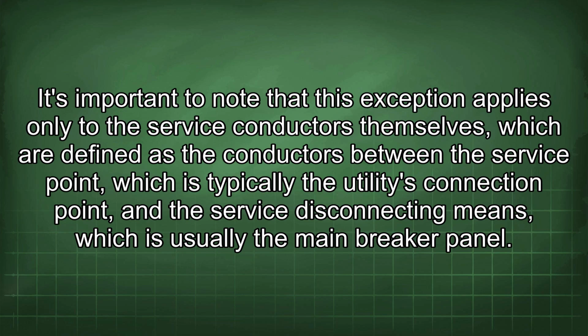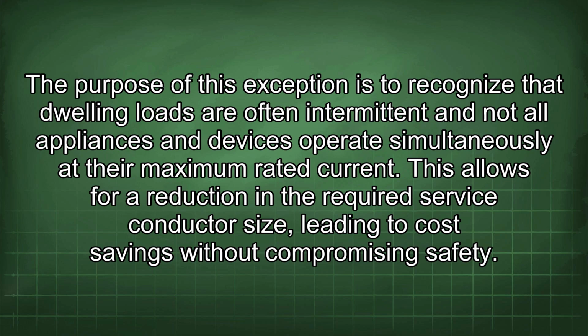main breaker panel. The purpose of this exception is to recognize that dwelling loads are often intermittent and not all appliances and devices operate simultaneously at their maximum rated current. This allows for a reduction in the required service conductor size, leading to cost savings without compromising safety.